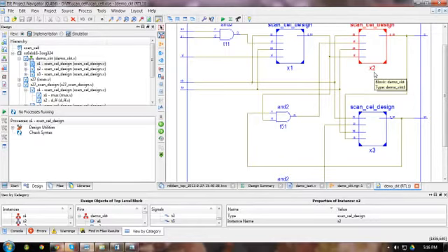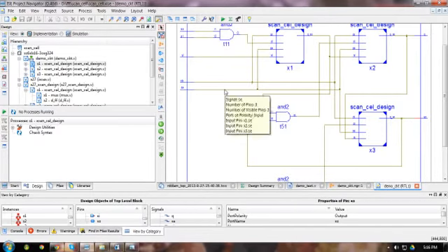It is captured. Now if you want to see whether this output is 1 or 0, directly you can take the output from Q, but Q is the output of the circuit. We have made a provision to see the scanned input and scanned output by giving another output called scan out here.